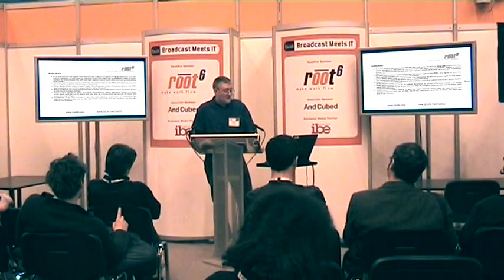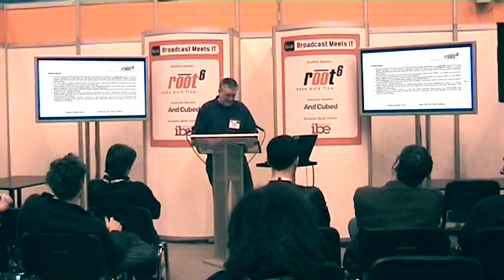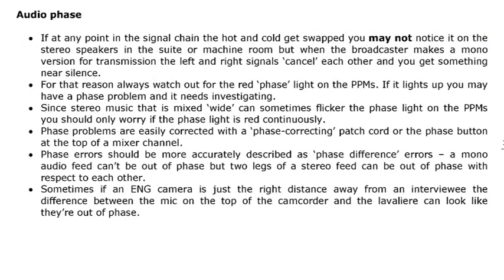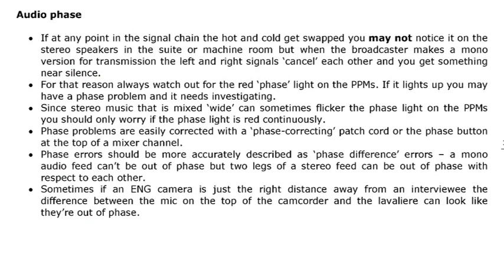The other thing you may fall foul of once you've got yourself a balanced facility is audio phase. So if you imagine that I've got a stereo signal, a nice mixed finished program ready to go to air, and inadvertently when you made the final copy of that program, the second channel, the hot and the cold conductors, were swapped over, either through a cabling fault or somebody used the wrong patch cord on the jack field, and now you've got a recording where, to a cursory listening, you can't tell that it's phase reversed.